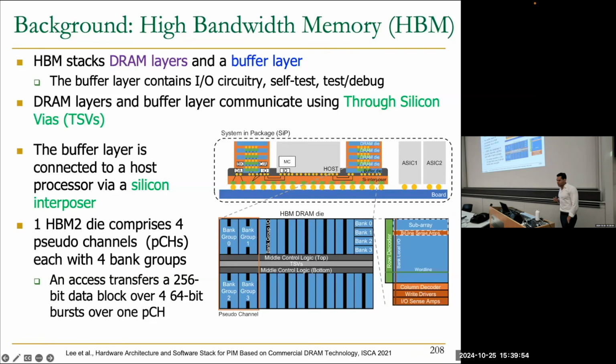realization of this chip, what we have is what is called pseudo channels. So some grouping of those TSVs, each one of them with 4 banks. And this is a little bit finer granularity than regular DRAM. This is wider because in DRAM the column transfer is 64 bits, and here it is 256 bits that is going to be used from a column read.